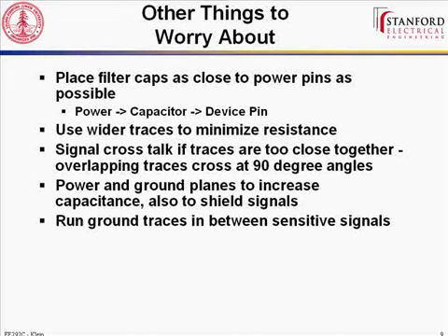Now, one more comment about the planes. You also have to worry about parasitic capacitances when you get to really high frequency stuff. I know some of you are interested in really pushing PC board technology. So you'll realize that if you have a fat trace or a plane going below a signal trace that's grounded or that's at VCC, there's going to be some capacitance between the two. It's a parallel plate capacitor. And that's going to affect your rise and fall times on digital signals going down those traces. Again, for everything we're doing in this class, none of this stuff really matters. When you start getting to really high-speed stuff, to high-power stuff, then you have to worry about all of these issues and then some.